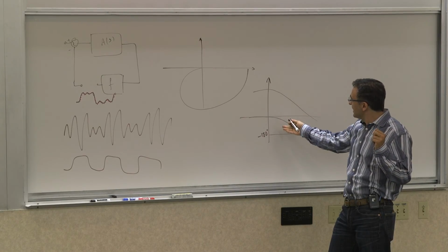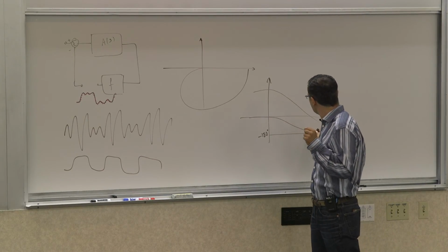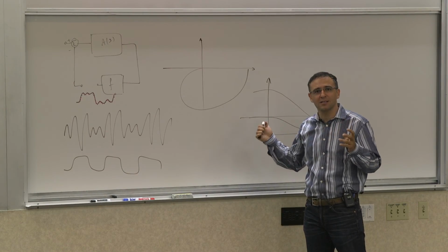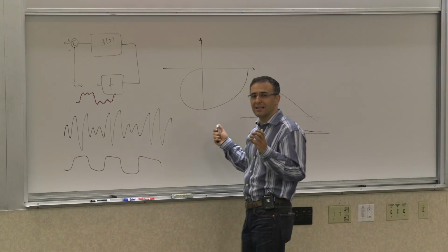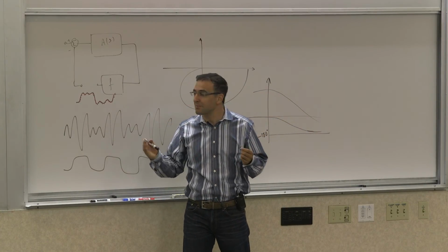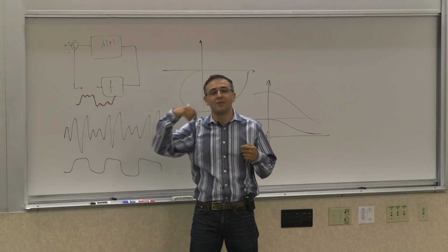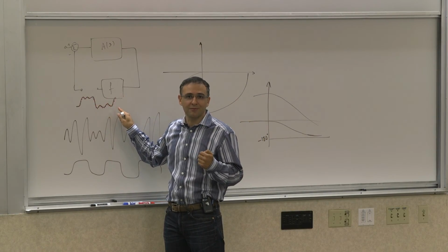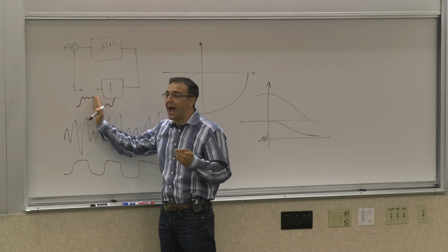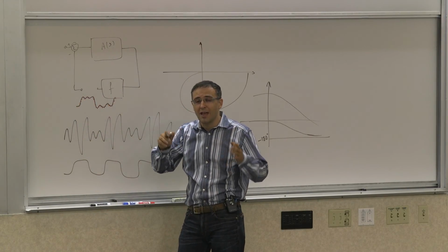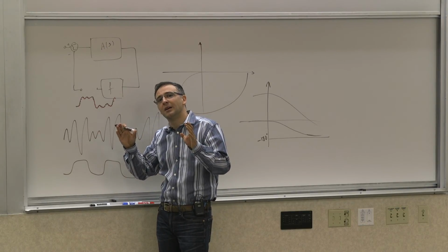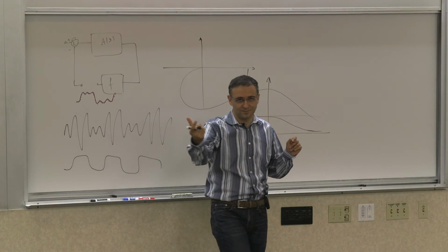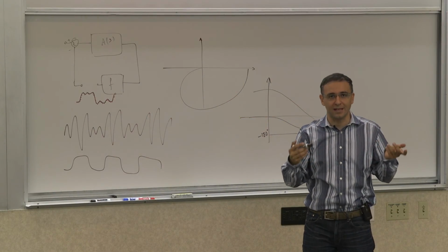But here's the interesting thing. In such an example, what happens in reality is, how is this possible? How is it possible that at no single frequency do you have something that comes back exactly in phase, but you maintain oscillation? The way it works is that individually, the Fourier components never come back in phase. But when you add them up, you can create a situation where the resultant waveform has a total phase shift of that much. More accurately, it's a time delay, not a phase shift.